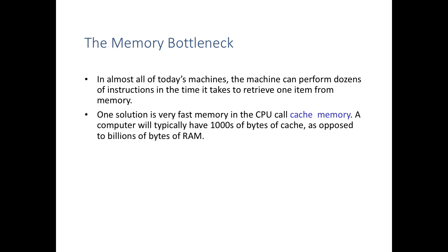If you have a memory bottleneck, that refers to the fact that you are I/O bound when you're doing your computations in your CPU. One way in which you can address the memory bottleneck and cease to be I/O bound is to have data transferred separately using direct memory access, or DMA as it's sometimes called. And what that does is it reaches out to the memory and stores the data in a high-speed cache. And the cache may be high performance, but typically it's relatively small.